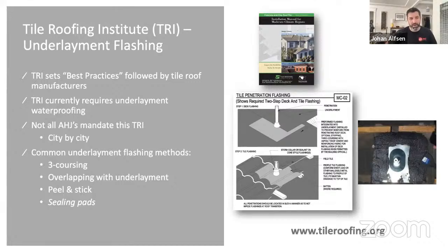There's a lot of argument going on in the solar industry whether solar roof attachments are attachments, quote unquote, or penetrations. And it's been debated because the definition of an attachment has different requirements as far as waterproof flashing, whereas penetrations have more strict guidelines for waterproofing to best practices and code compliance.